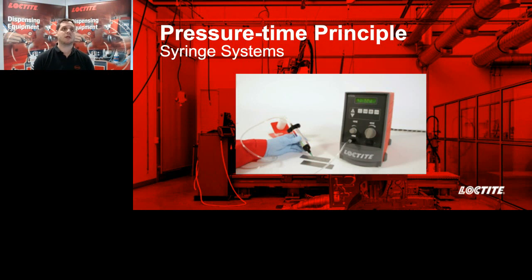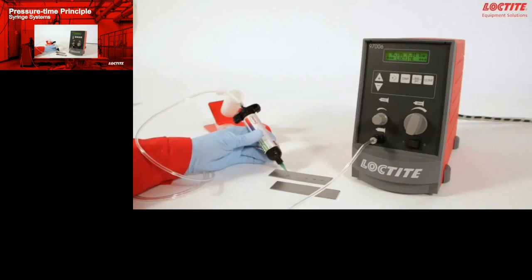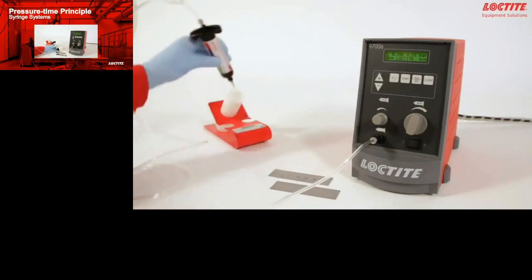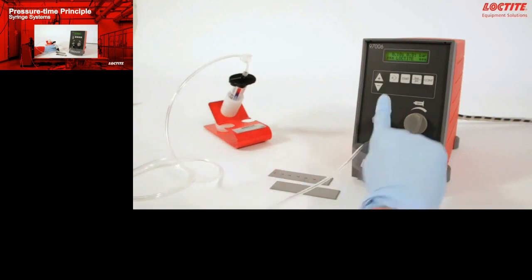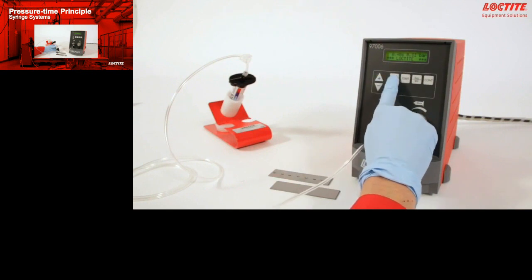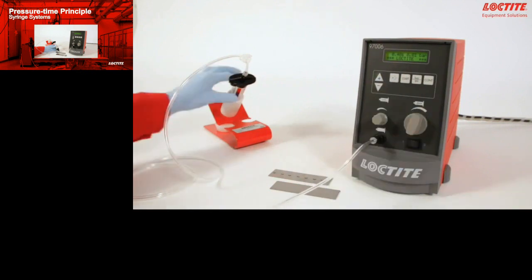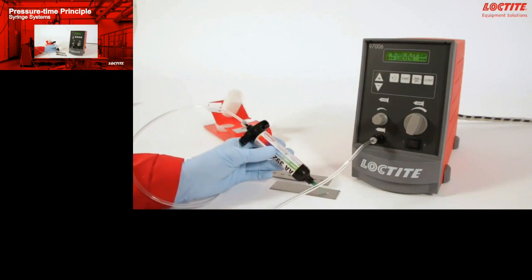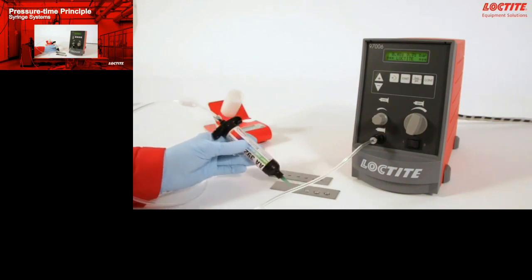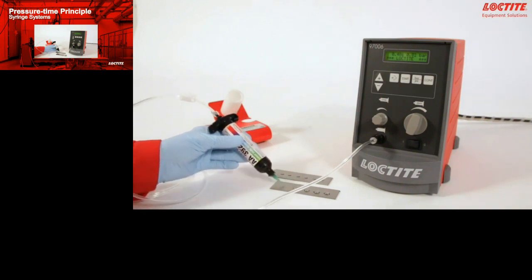We now move on to our second video. This time it's the digital syringe dispenser in action. And again, what we'll see is some dots, a change in time, and higher dots. So you can see the operator has dispensed some dots precisely and accurately. He's now increasing the time of dispense. He'll confirm that new setting by pressing the Enter button. You will then see him dispense some more dots precisely and accurately, but the dots have increased due to the increase in time of dispense.